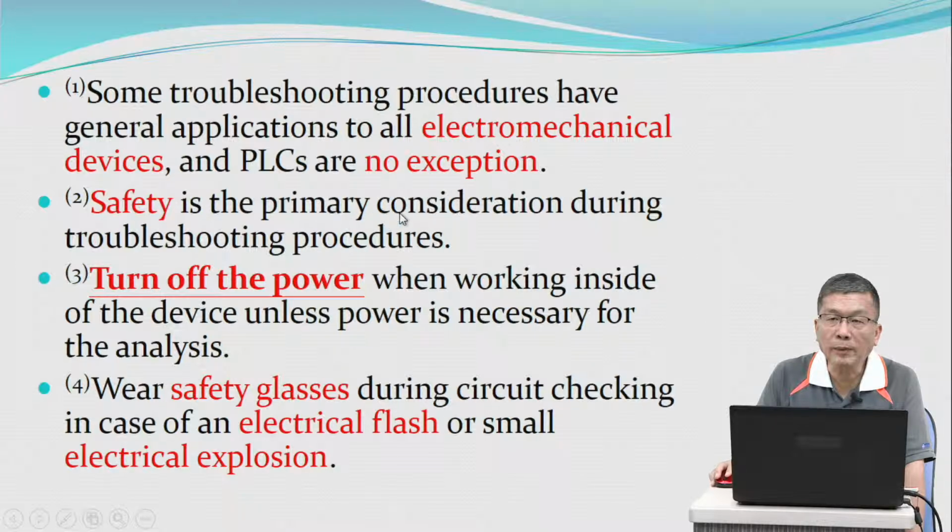Safety is the primary consideration during troubleshooting procedures. Turn off the power when working inside of the devices, unless power is necessary for the analysis.